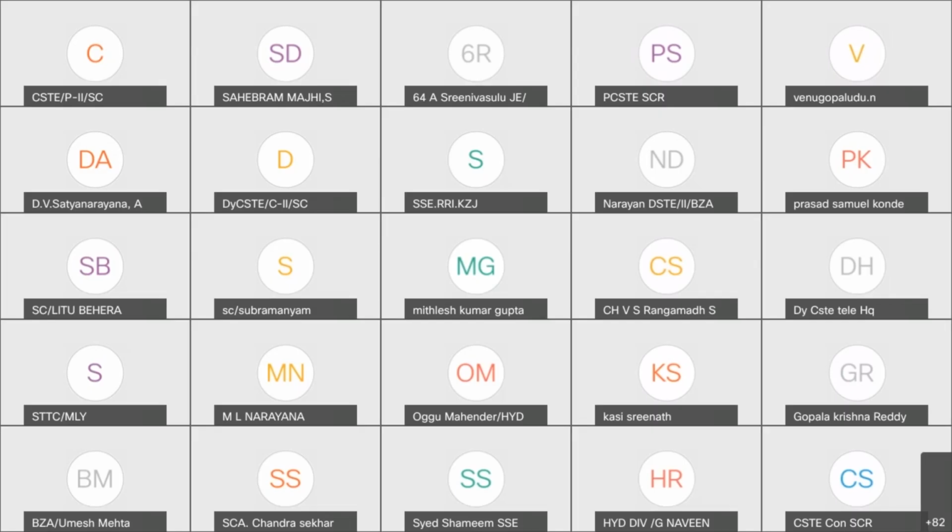Anybody else is facing problems due to the inconsistencies that Ram Prakash has already told? Actually, the throw lug has been supplied for both ends, sir. But for RH and LH, for both types of point machines, as per requirement we are cutting this throw bar lug, connecting the throw bar and throw slide lug, sir.